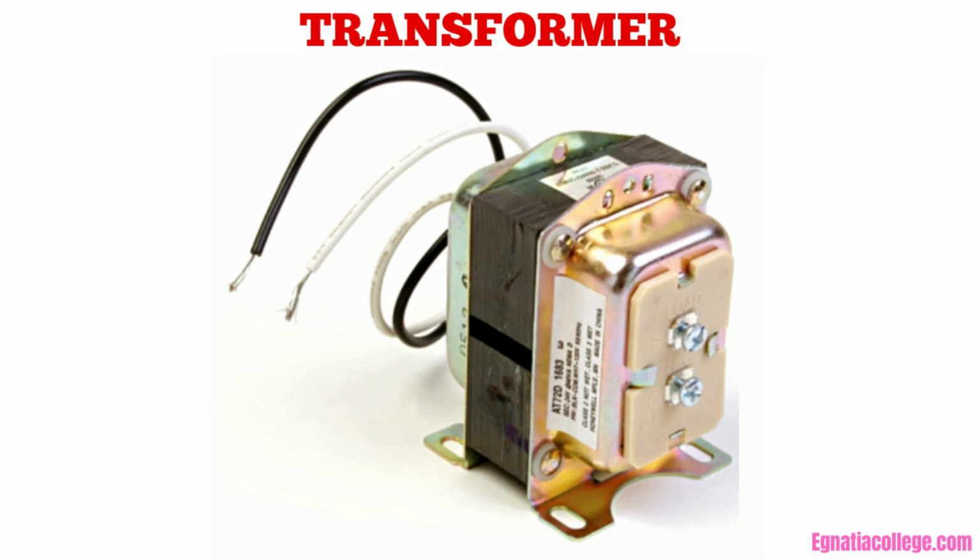Transformer. A transformer transforms the branch circuit voltage to extra low voltage. For residential applications, these are Class 2 transformers, 120 volts to 24 volts. The low voltage wiring on the secondary of this transformer is Class 2 wiring.